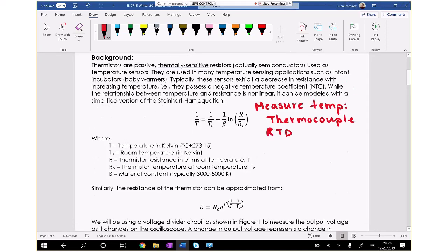So the relationship between resistance and temperature here is pretty linear. All right, so that's a good thing, because as we'll talk about with a thermistor, it's not linear. They aren't very expensive, so that's good. But one of the issues is that there isn't a lot of sensitivity. And what that means is that with a change in temperature, the change in resistance is pretty small.